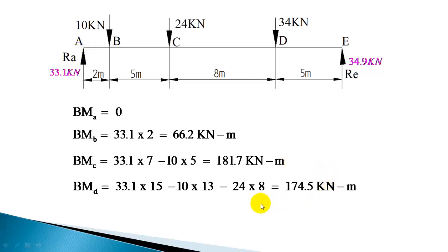So you understood the bending moment, all the salient points, and the nature of variation is going to be linear variation for bending moment, because point loads are acting, so the variation is also known. Now you can plot the shear force diagram and bending moment diagram.